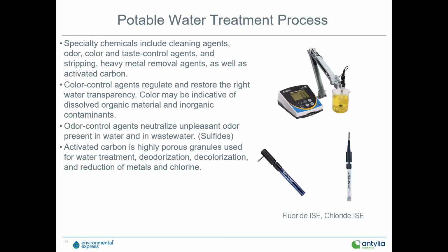Many of the older, bigger cities have lead laterals from the main water supply line leading up to residences and businesses, and it's very important that as we move forward, they remove these lead pipes and replace them with copper or iron, and reduce that amount of lead poisoning.